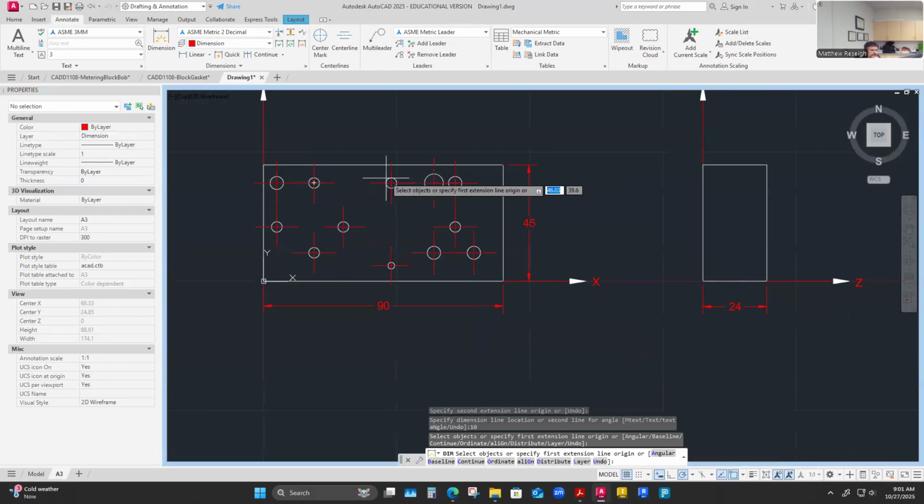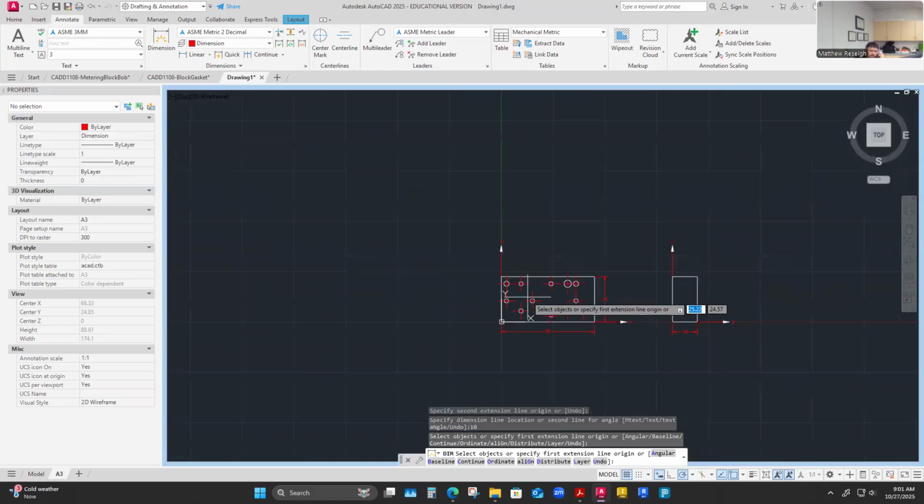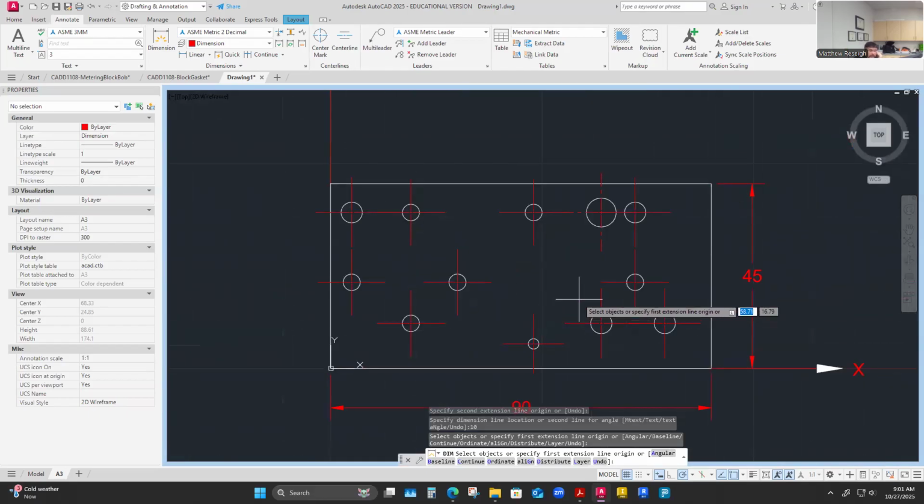I think I still have to do some line type scale. That's what it looks like there. Well, I'll go back and start building my table. Well, I could start labeling these though while I'm in here too. So I could build one, because every one of these has to have a feature label. If I'm going to table something, I have to give my feature a unique name.